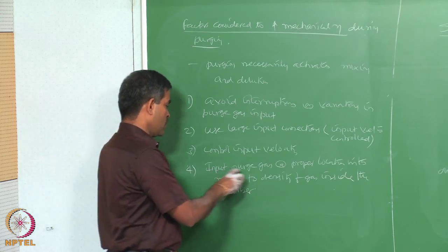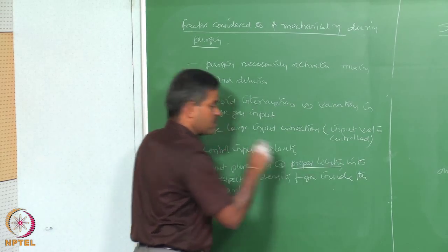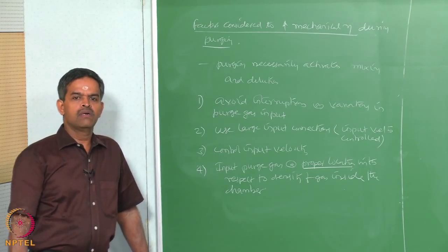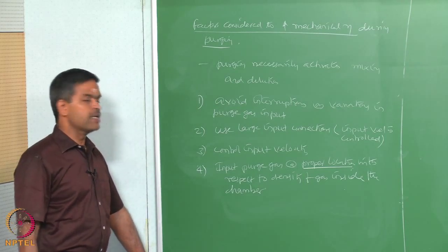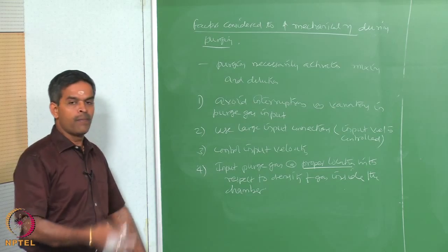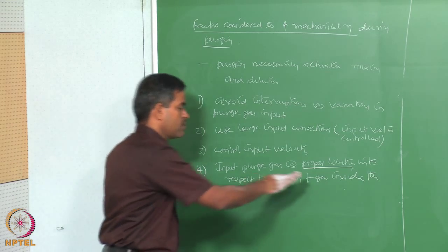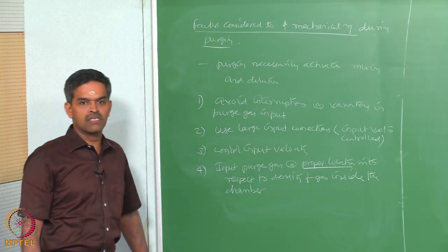So, introduce the input purge gas at a proper location, either from the bottom or from the top or from one end, pushing the purge gas to the other end, so that you ensure a proper mixing of the purge gas with the vapor or the gas present inside the chamber.